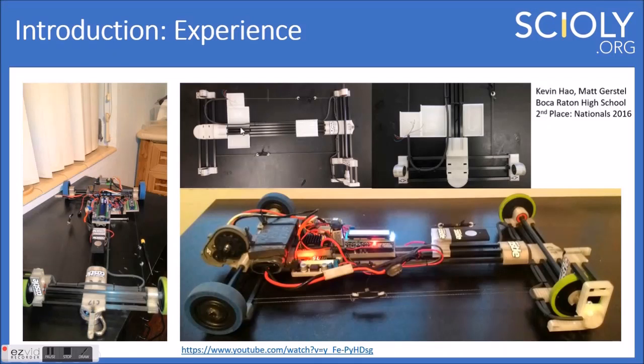And then you can also see the wheelbase, which is the distance between the front and rear axle. And that's connected by these 5 carbon rods here. It's a little bit hard to see in this top photo, but if you look down over here, you can see how it's almost like a pyramid shape, just missing the top rod. The reason we went with this kind of weird design for the chassis was we wanted some flexibility in the frame to compensate for any imperfections in the track. And it worked out really nicely, and it was quite light, very strong, very flexible.